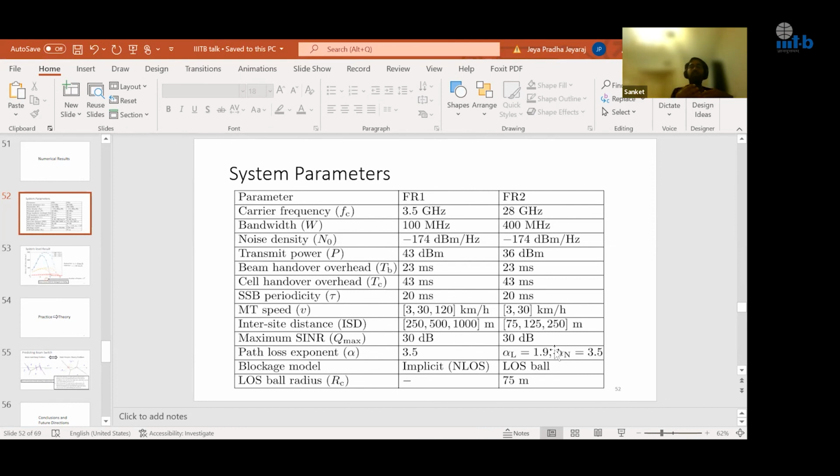Because you know what happens, we have the uplink and downlink, right? In 5G, they use time division duplex. And usually the famous slot structure depends on the subcarrier spacing, meaning the slot duration, whether you're operating in a 2.5 millisecond, 5 millisecond or 10 millisecond slot. It depends on the subcarrier spacing used, 15 kilohertz, 30 kilohertz, and so on. For ultra reliable, one has to use a very small slot duration, so one has to use a higher subcarrier spacing, could be 120 kilohertz, where the slot is 0.25 millisecond, I suppose. Then it depends how you schedule the user depending on the downlink and uplink.